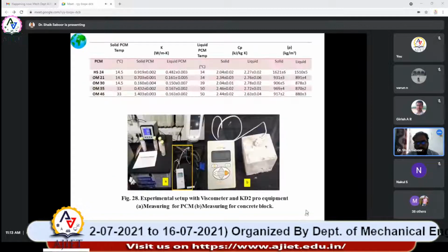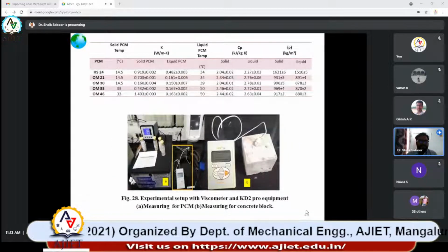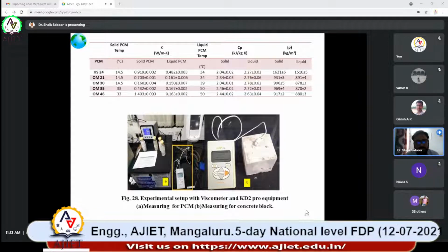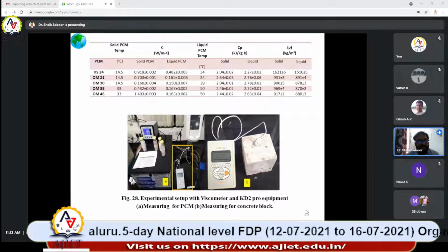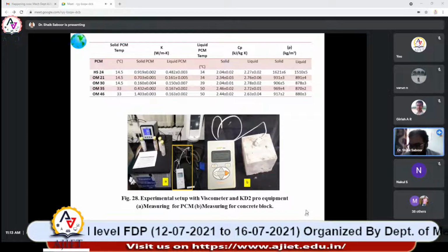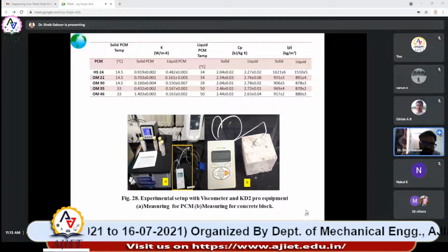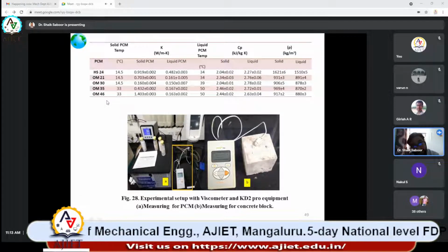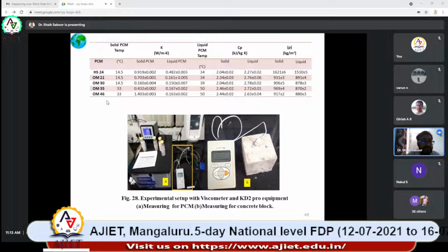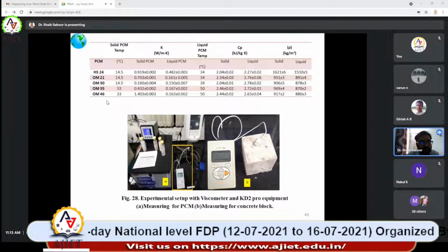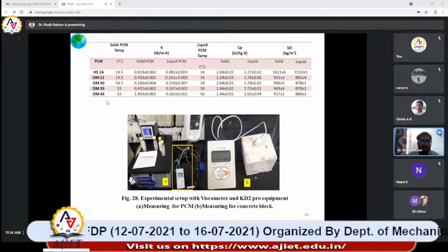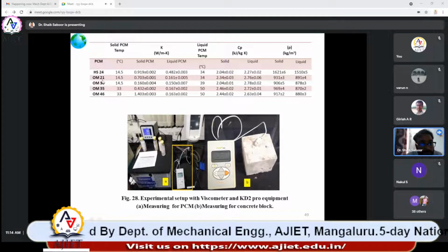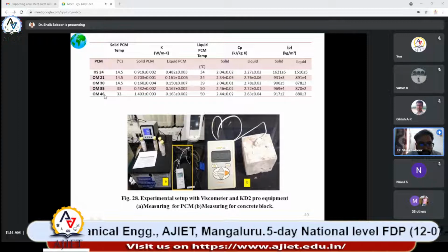We tried for buildings, where the most acceptable melting point of the phase change material is less than 30 degrees centigrade. Using less than 30 degrees centigrade is advantageous, but we tried 35 and 46 as well, in order to see the performance. We tried 5 different phase change materials: hydrated salts of melting point 24 degrees centigrade, and organic mixtures of melting point 21, 30, 35 and 46.